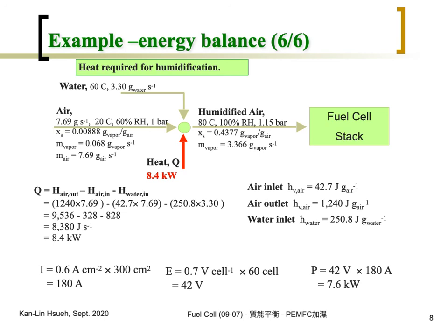The exhaust gas is warmed air and the effluent fuel. So actually the exhaust gas can do the heat exchange with the dry air. So actually, the heat required is recycled from the waste heat from the fuel cell output. So actually, there's no additional heat required.